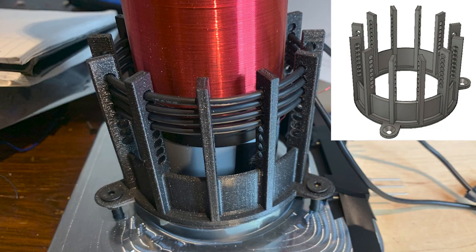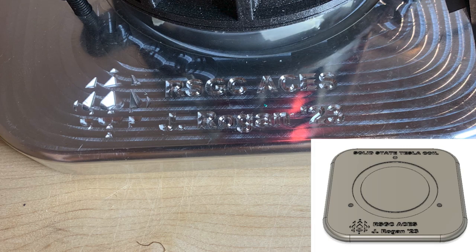Next, the primary bracket is custom designed in Fusion 360 and features 12 vertical shafts with holes in such a way that the secondary winding is guided and supported as it moves down. The primary bracket is mounted on a custom CNC machined aluminum base plate designed in Fusion 360 and manufactured by Argon Prototypes. The function of this plate is twofold. It is a ground plane for stray voltages, and also the MOSFETs may be mounted to it as a heatsink so long as they are attached with electrically insulated thermal tape.